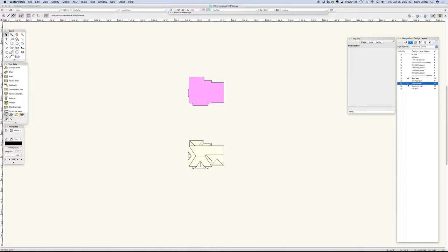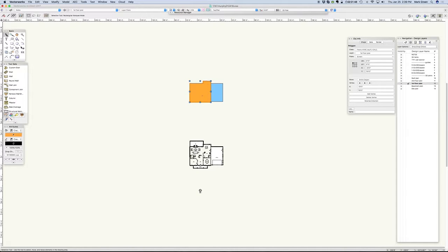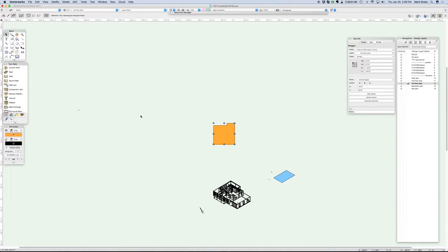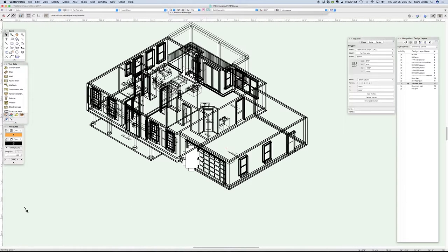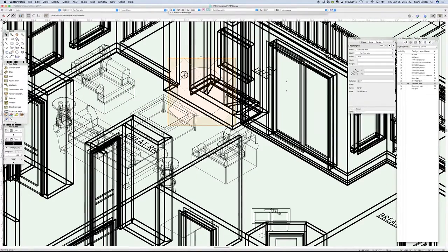Again, when I was on the first floor, I would also probably do this in isometric. And if I see something that is flat like this, that should not be flat, that should be in layer mode. So I would ungroup it and then take it from screen mode to layer mode. Same with this table and chairs. It should have actually been a plug-in or a symbol, but somebody did it with just shapes, so that's fine.